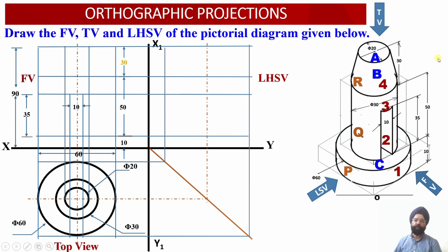Now this corresponds to the circular element number 2. This is the outer portion of element number 2, and having drawn the circle in the top view, I am going to take up these projections so that I am able to obtain the bottom point of element number 3 over here. So this was my slant circular portion. The top portion I had identified earlier.